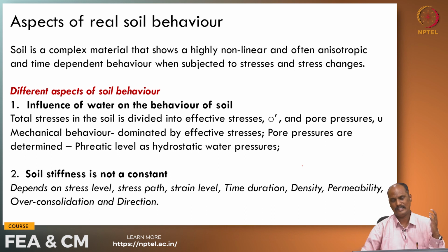We will discuss the different aspects of real soil behavior on a point by point basis. Very firstly, the influence of water on the behavior of soil. We all know that we have the total stresses, the effective stresses and the pore water pressure, and as geotechnical engineers or civil engineers, we know the importance of the computation of effective stresses.